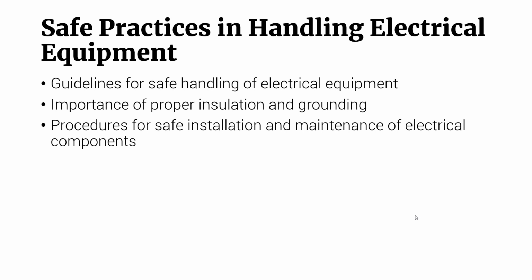Baka naman magre-repair ka ng motherboard, magre-repair ka ng PC, naka-on pa AVR, nakasaksak pa yung power cable niya. 'Di ba? Baka makuryente ka naman. So make sure na naka-de-energize siya, naka-off yung AVR, naka-off yung power supply niya, nakaalis siya sa tawag dito, saksakan. Okay? Use insulated tools and wear PPEs when working with live circuits.